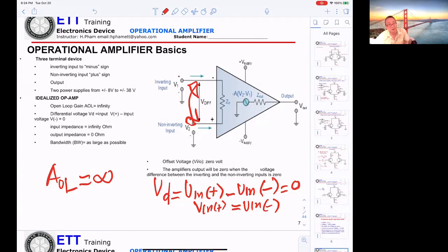And now I'm telling you what that means for open loop. Open loop gain means you get the IC op amp and they don't connect anything to it. Then the gain they get is called open loop. And that gain will be given by the manufacturer. We cannot make it up. They sell the op amp, they tell you what the open loop gain equals. Okay?